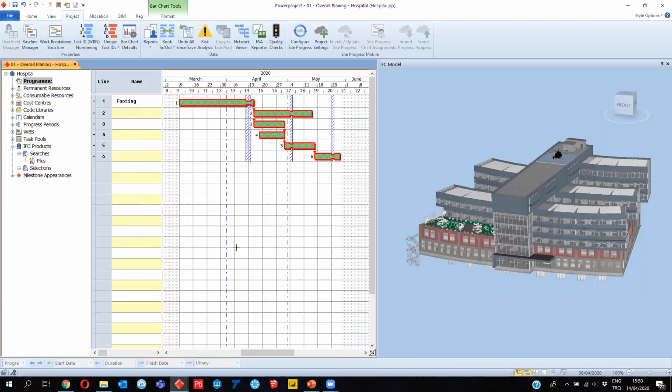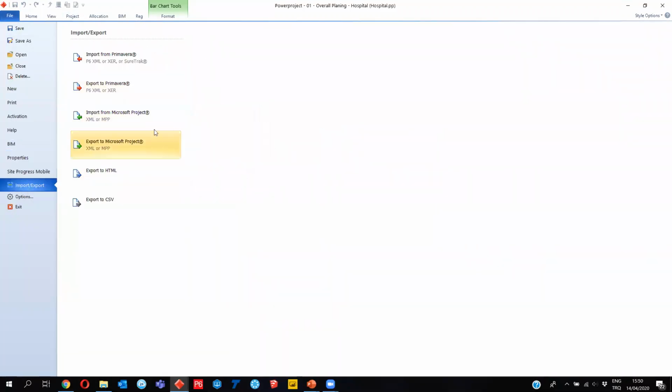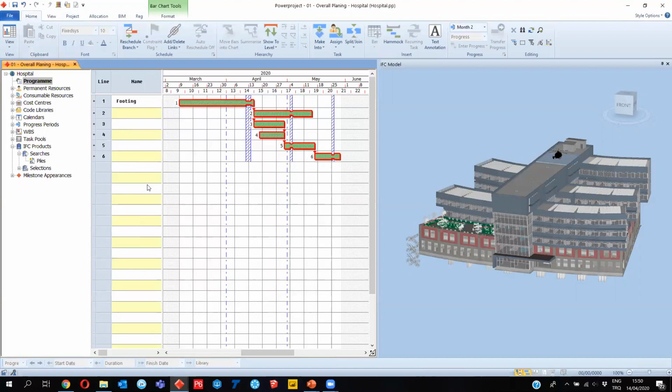You can go into the Revit software, go to the file menu, and export your 3D BIM model as an IFC file. And I believe other design software like SketchUp also has an IFC exporter embedded.